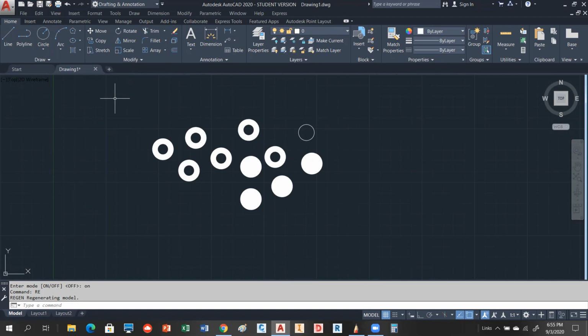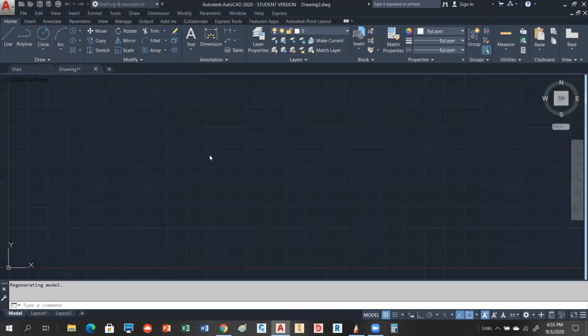So let's look at new. There's two ways to generate or begin a new drawing. The easiest way is to probably just click on that plus right there, and it automatically generates a new drawing for you. It doesn't ask you any questions, you just go. So you need to understand what it's using. When it opens up that drawing, it actually uses another drawing called a template file. And that template file is called acad.dwt. So what it does is it brings in certain settings automatically, like for instance, settings on your units and settings on your other objects that you might have.